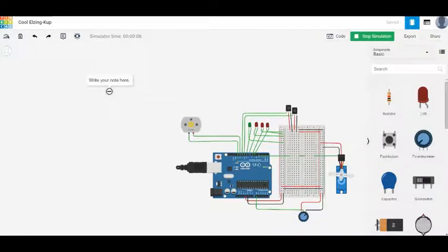The stepper motor is connected to the proximity sensor, which helps in detection of distance between the arm and bottle, and is in turn connected to the potentiometer, which finds distance. As soon as the proximity sensor reads zero distance, the stepper motor runs in the reverse direction. And as soon as the stepper motor comes to the original position, the DC motor starts.